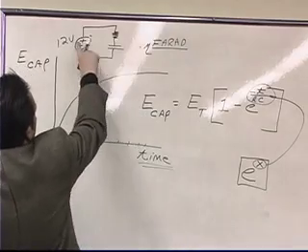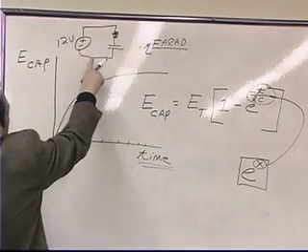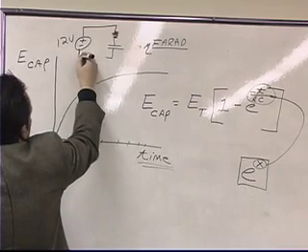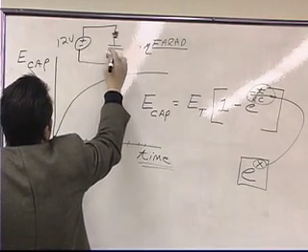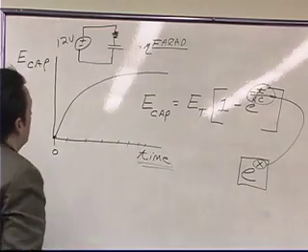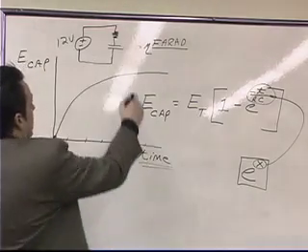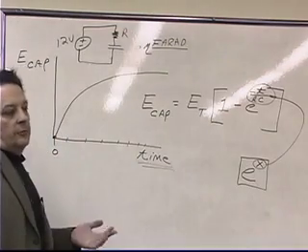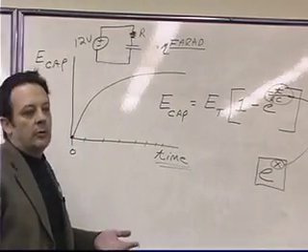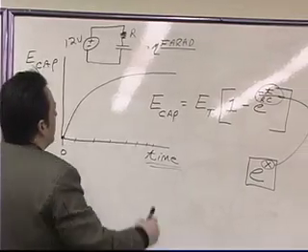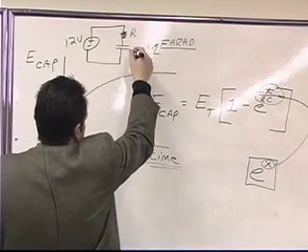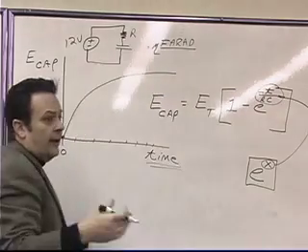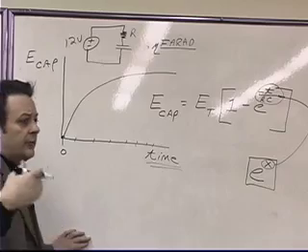So if we look at this circuit right here, it's really the same circuit that we had before. All we've done is lump the resistance of the wire into one resistor. It might be a very small resistance, maybe 0.05 ohms. And then the capacitance is going to be some number of farads or microfarads or millifarads or nanofarads.